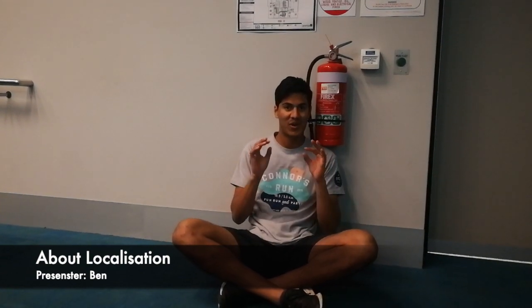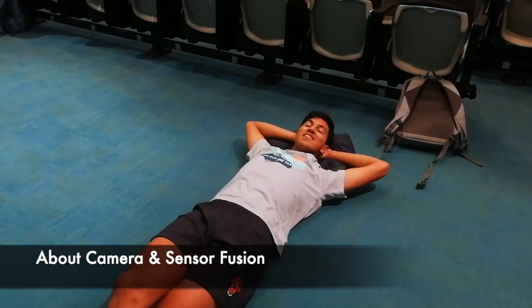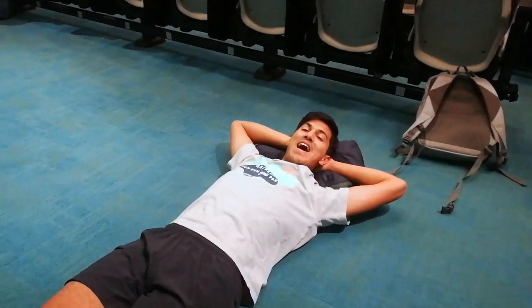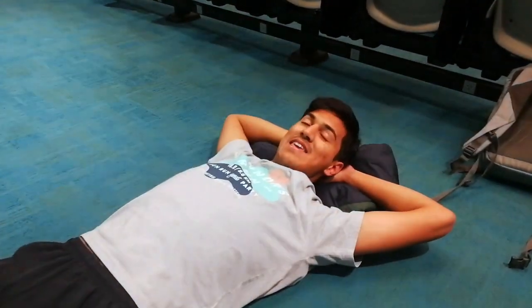To figure out where we wanted to go, we first had to figure out where we were right now. That part is localization, and the way that we went about localization is using a rotary encoder. This little device that sits in a wheel and counts how many times it takes to make a full revolution. Our encoder let you see 3,600 clicks per revolution. Wow, such high res. Still though, it was an incremental encoder.